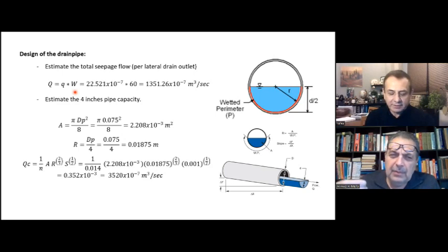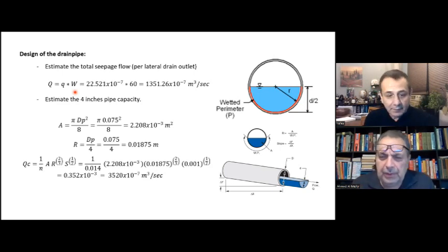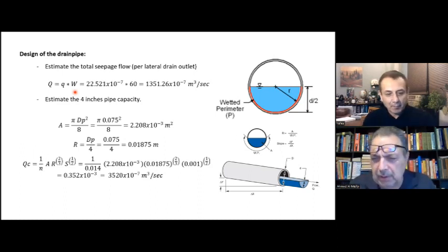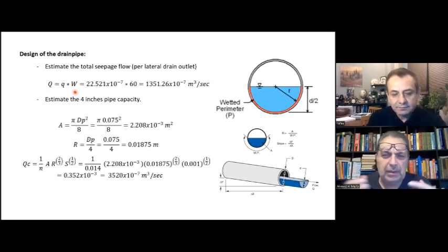Right. We know what the filter requirements are, but how to establish the whole thing, geometry, flow. Of course, it starts with the flow net, with the Dupuit theory. Then you end with the pipe size. You end with the filter material. You end with the filter geometry. You know your margins. You know what materials you're buying from the market. How you're getting the Froude number or the Manning's number.